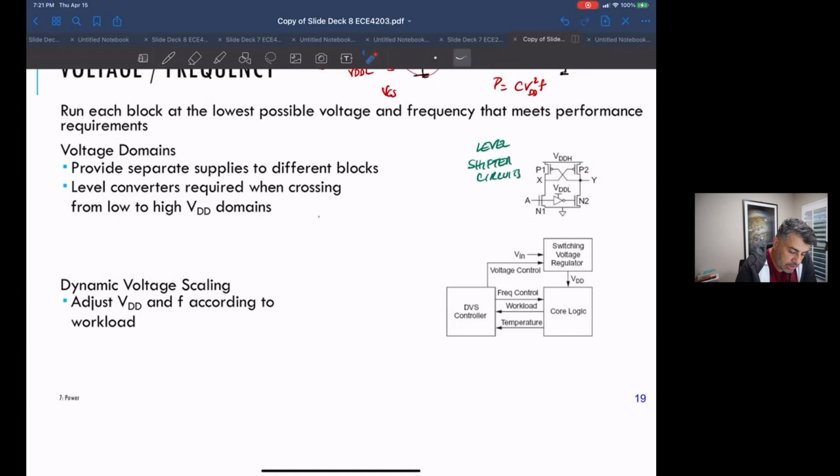These have positive feedback PMOS transistors connected on top, which go to the high supply. What they do is translate the low signal level to the high signal level at their output. You have to be really careful designing these, but once you have one, you can stamp them out all over the place. You have to make sure you use these or you're going to have some serious problems. And it's not always easy to see in simulation that you did this.